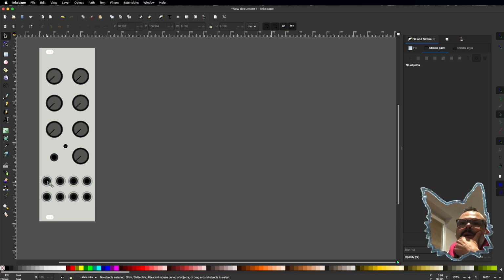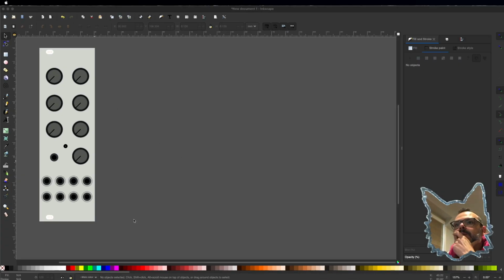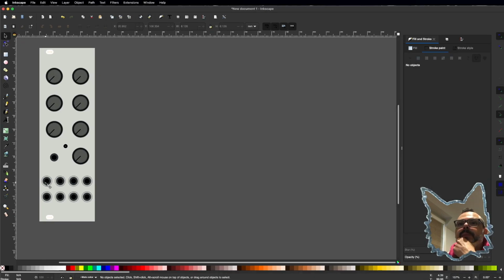Then over here, we could allow an input for the VCA, right? So then that way we could use this as a VCA if we wanted. We could allow output of the envelope, each of the envelopes, 1, 2, right? And then we could also, I forget what this one is. Let's see. So we could do actually the inverted envelope output, right? So we could have an inverted out, the regular, and then the output of that second, just the release one. So yeah, this could give us a few more extra options for usability in here.